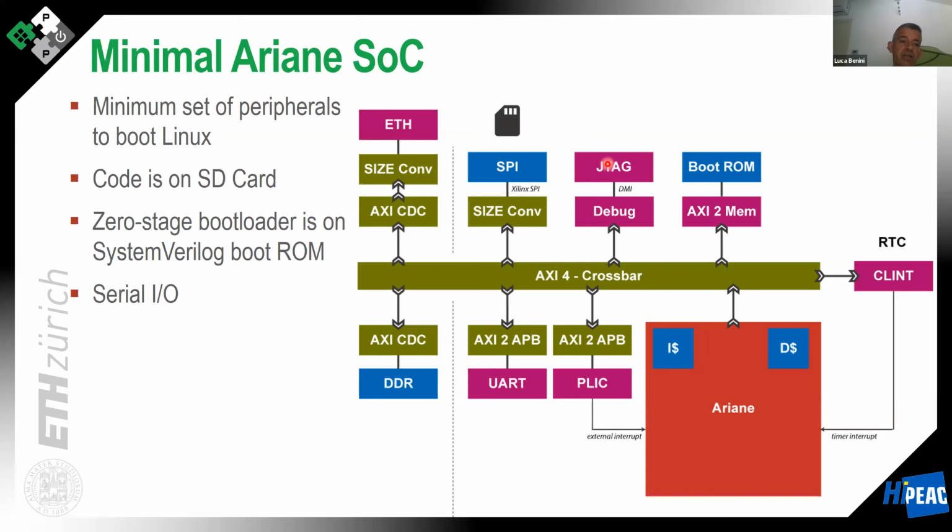This can be relatively easily implemented on an FPGA, which already provides you, for example, the physical memory controller that you need in order to access DRAM. And if you want to support the open source core, you have to provide an FPGA bitstream so that people can download the bitstream and get working on your emulated SoC to get their applications ported on FPGA, tested and debugged.